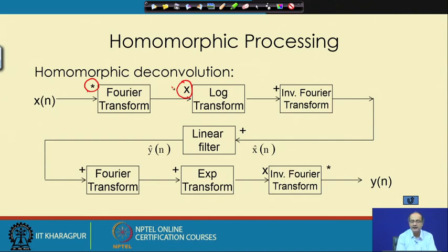The constituents are now combined with the multiplicative operator. So, after taking the Fourier transform, we get rid of the convolution operator and the constituents are multiplicative components. Now, to remove the multiplicative operator, we take the logarithmic transform, or complex logarithm, and that gives us the form where the components are combined with the addition operator.